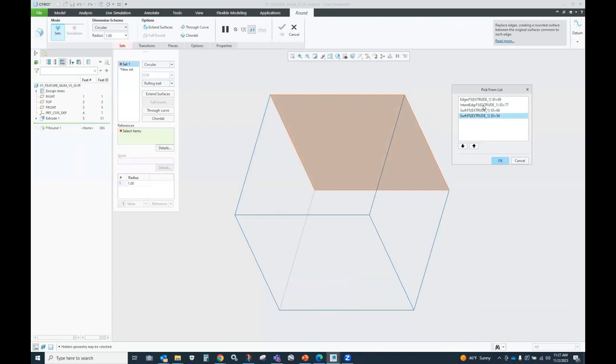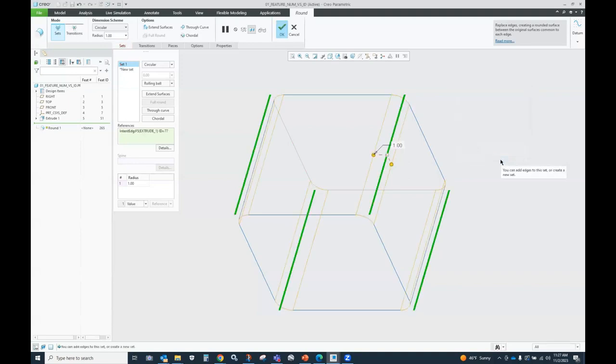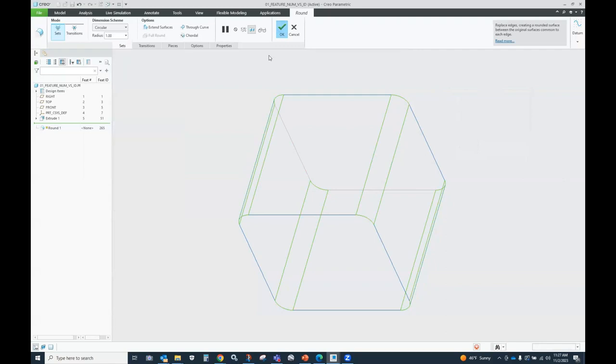But then there's this thing called an intent edge, and it has an ID of 77, but it is not assigned to any piece of geometry. It's a collector of geometry. And if I pick on that, you'll see that all 4 of those edges have been collected in that intent edge selection. And I can say, okay, there to select all of those at once, and then okay.